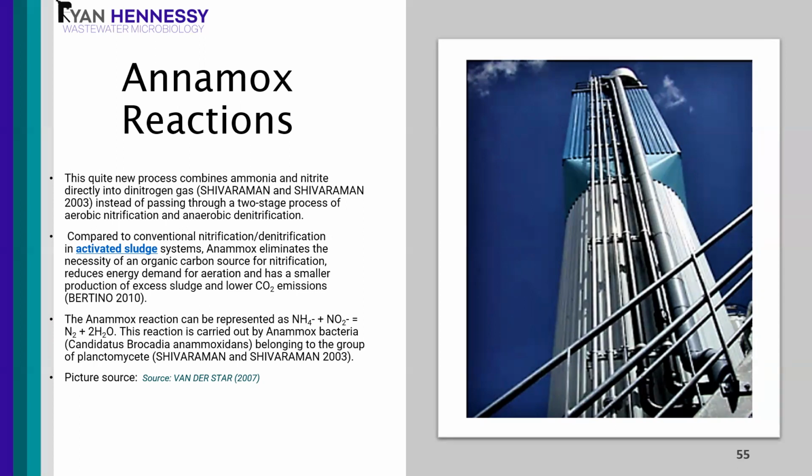Compared to conventional nitrification, Anammox eliminates the necessity of an organic carbon source, which is also beneficial, and it reduces the energy demand for aeration, has a smaller production of excess sludge and also lower CO2 emissions. But Anammox is finicky.